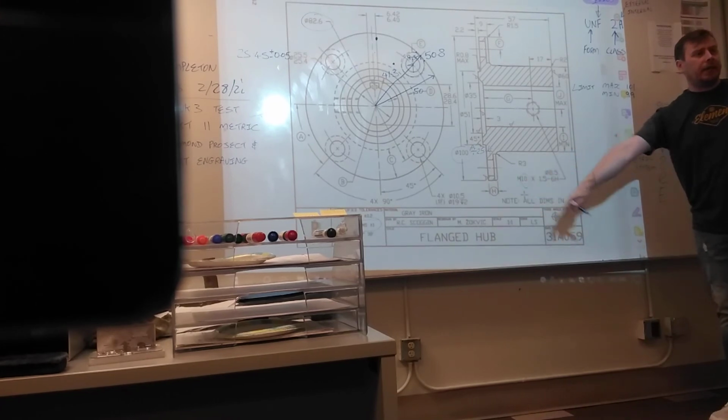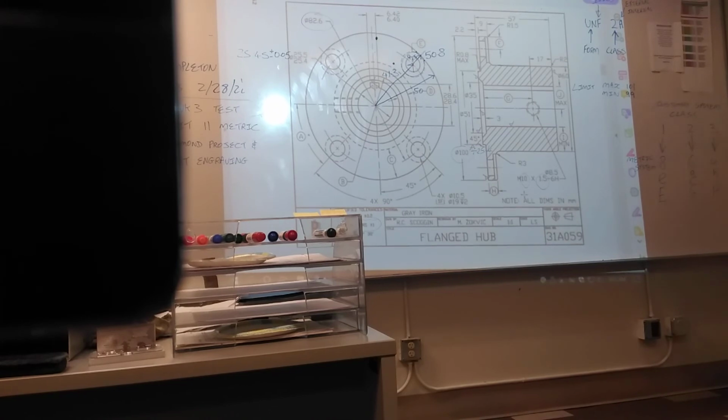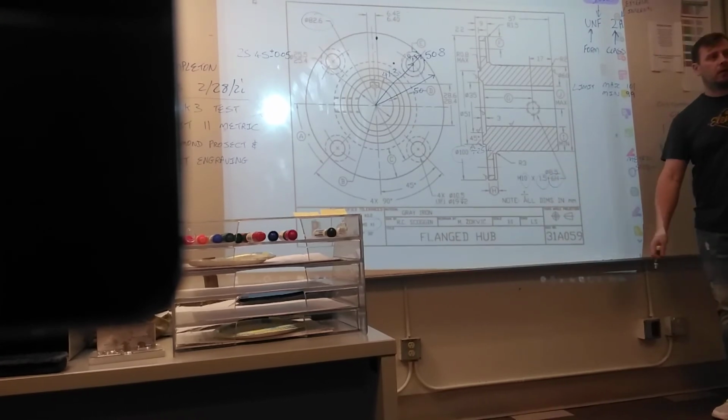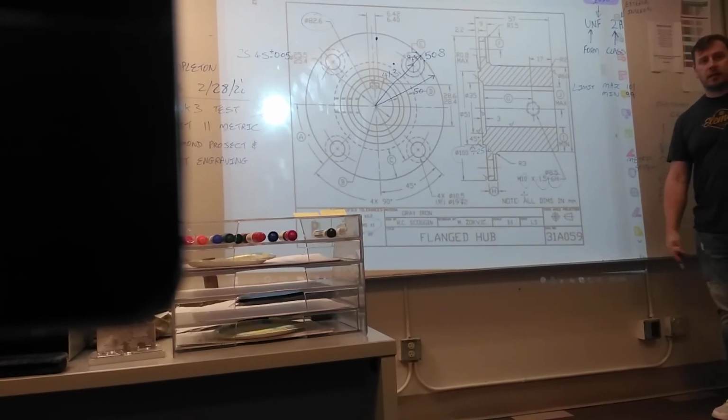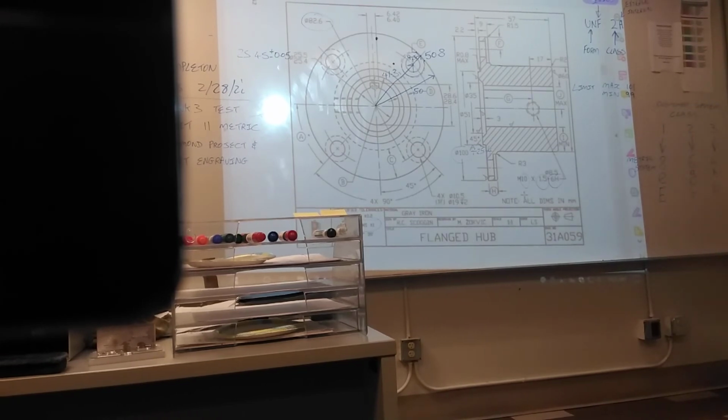What is the pitch of the threads? 1.5 millimeters. What is the tolerance class? 6H. That's it.